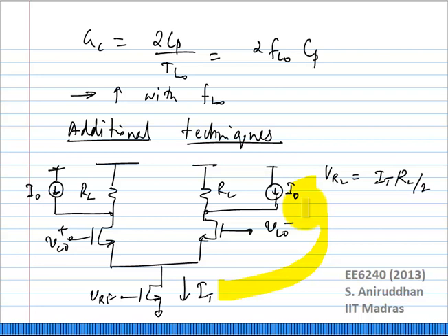The device size will become very small, and for a given current, the current may be fixed because there is an upper limit on the amount of current, which is IT. Right? So what happens to the VGS minus VT of these devices? It may get very large, okay, but it really is a function of I0 and IT. What happens to the output linearity?